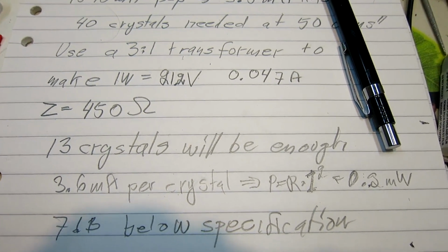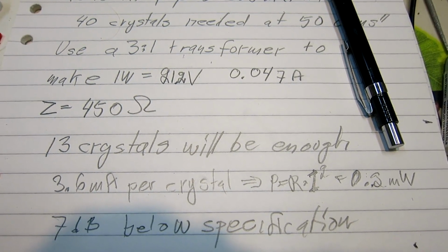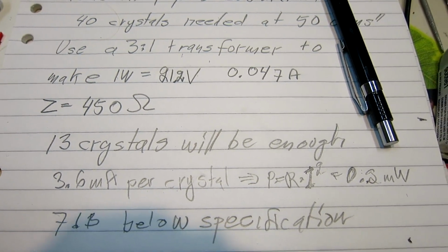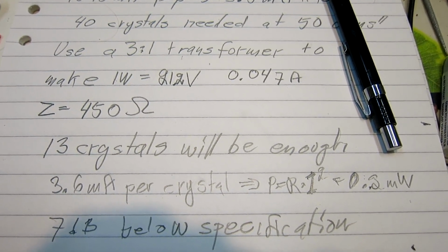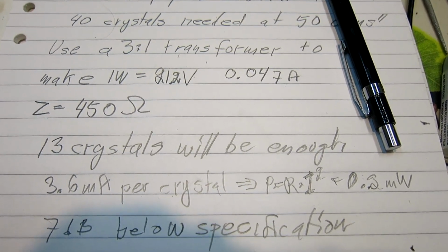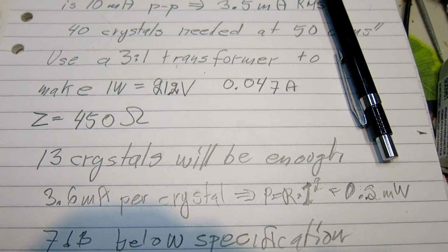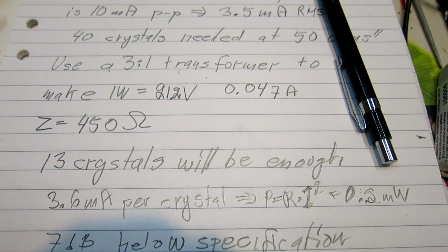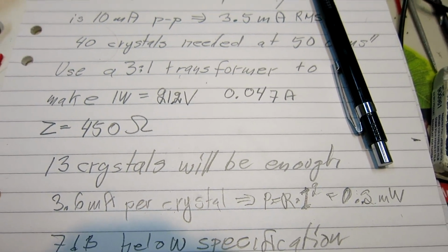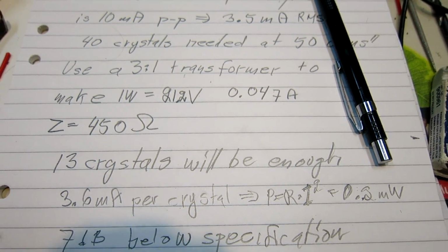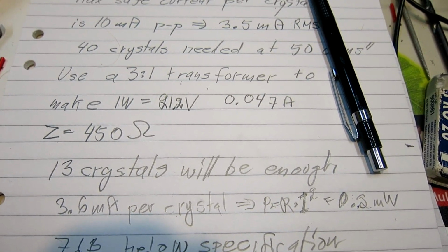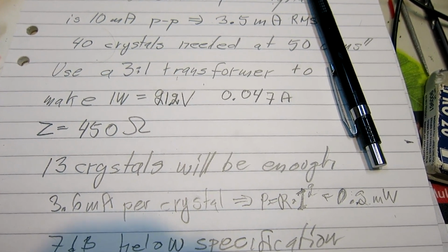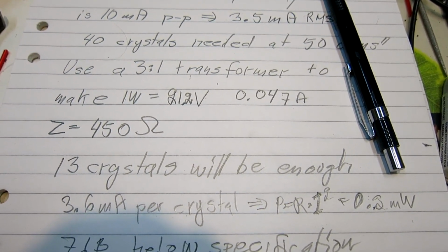The drawback of this is that the bandwidth of the notch will be 3 times bigger, so I cannot measure close spaced noise anymore. The previous notch operated at 50 ohms would give me the noise sidebands down to about 2 kHz from the carrier. And now I will not be able to see closer than probably 6 kHz or something like that.